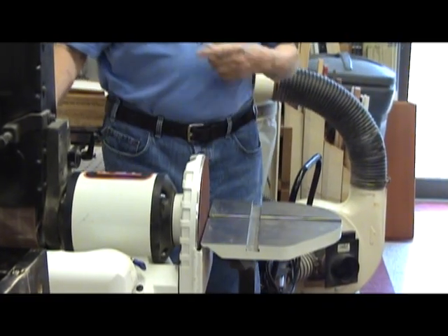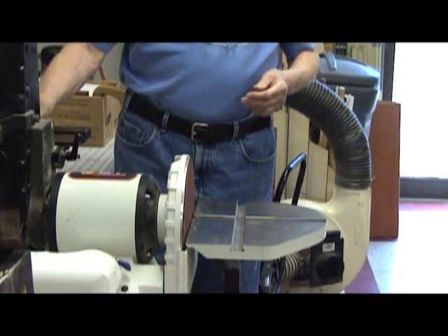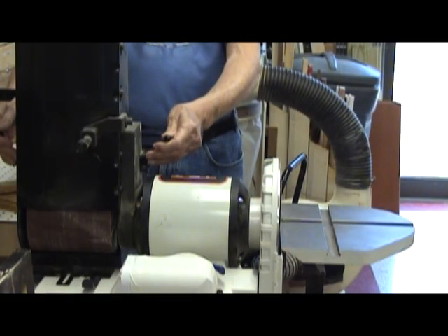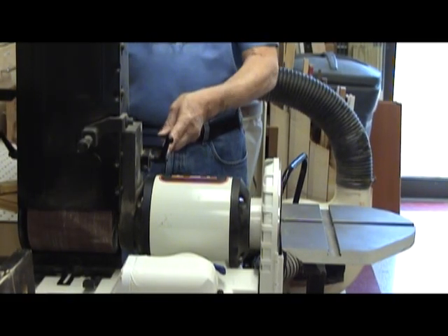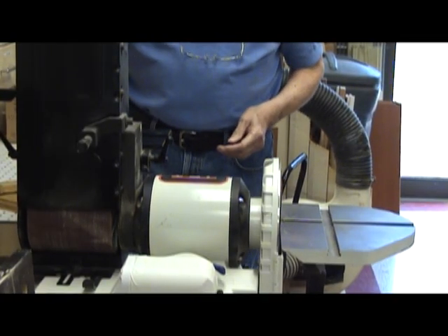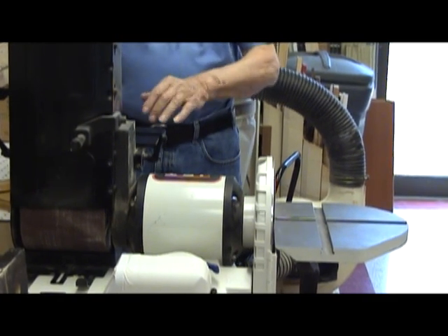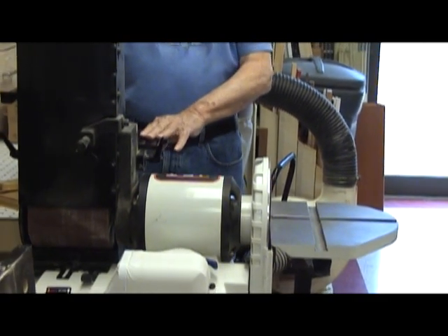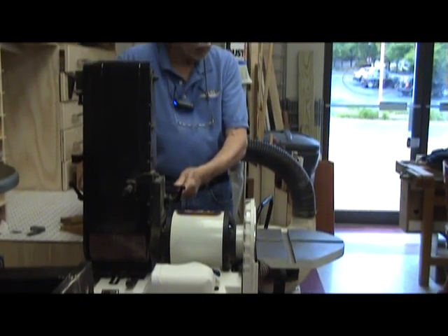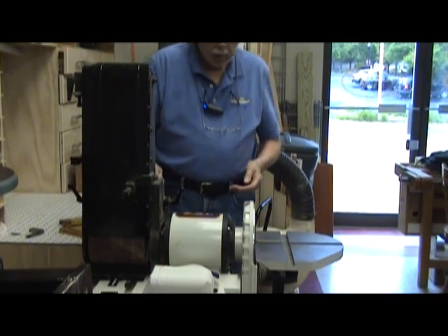Bob and I did an adjustment here earlier tonight to get the belt square, and there are two knobs here that will relax it, then you can tighten it back. Should you go about making a change, make sure that the fence itself is 1/64 or more away from the belt. Otherwise, we're going to wear down the aluminum here of the fence.